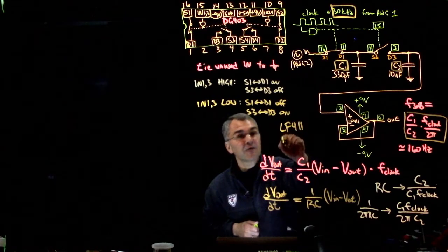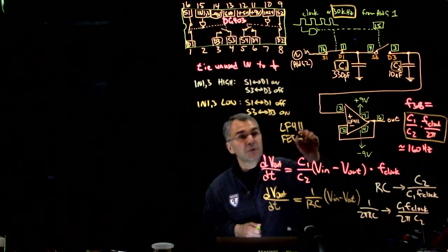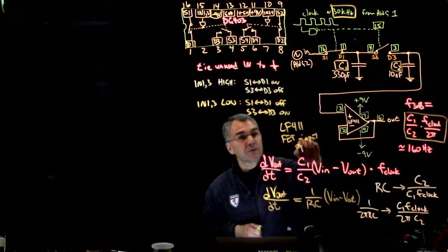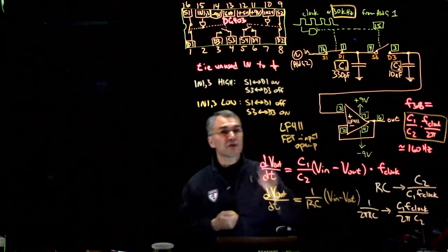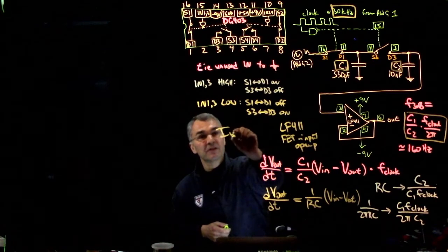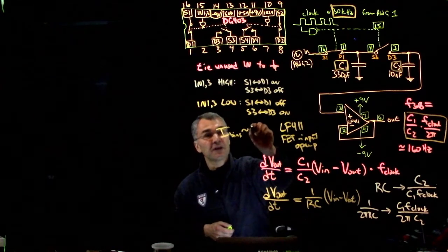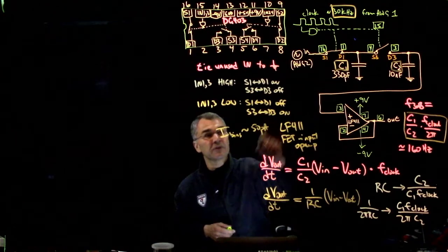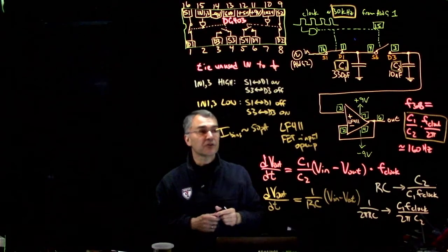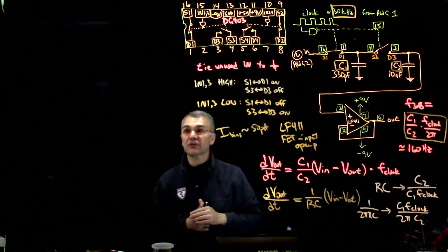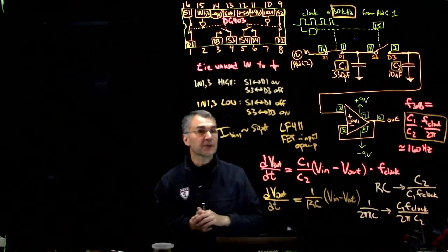This is a FET input op amp, and it has an absolutely tiny I bias, right? I bias was on the order of, I think, 50 picoamps is the spec, something like that. So it has an absolutely tiny bias current, and that's due to its field effect transistor input.